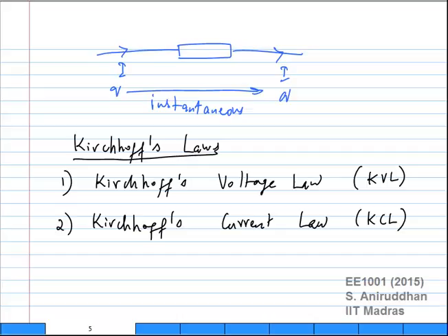Okay. We do not look at distributed quantities. So Kirchhoff's laws, for example, may be violated in certain cases, but we will not consider those cases in this course. As far as we are concerned in this course, KCL and KVL are always valid. Of course, there are certain cases, as we pointed out last time, for very large systems at very high frequencies, where this is not valid.